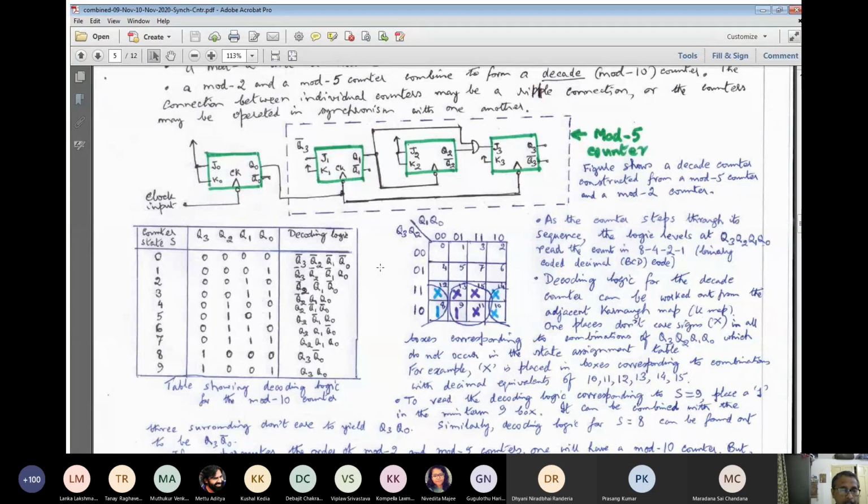Also, in a general industrial system, when a controller is passing through a particular state, a motor can be turned on or a furnace can be turned on. So different operations take place at distinct states of the controller, and always there is a counter at the heart of the controller. So we need to decode each of the states of the counter, at what state the counter is resident now, and accordingly we issue out the control signals.